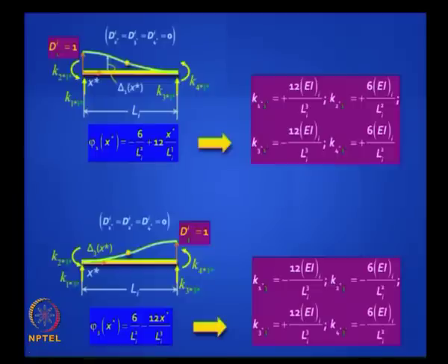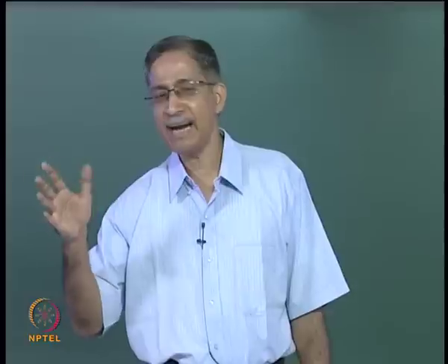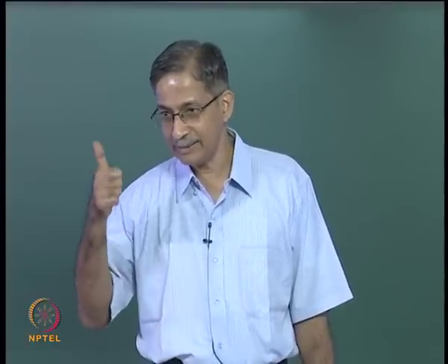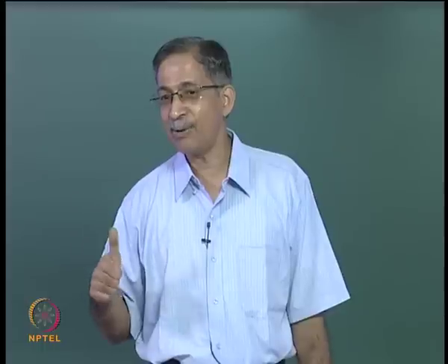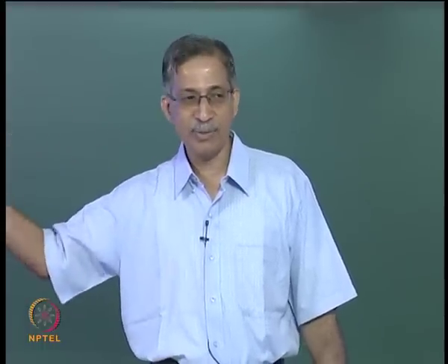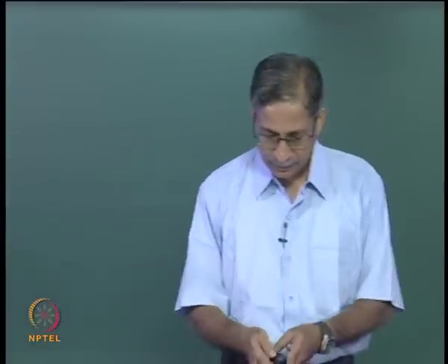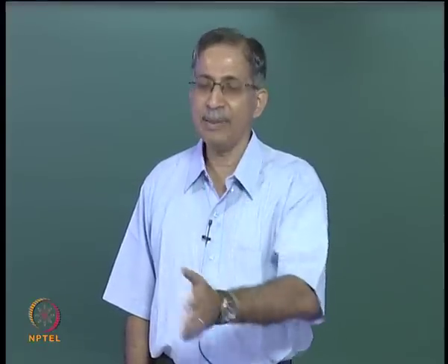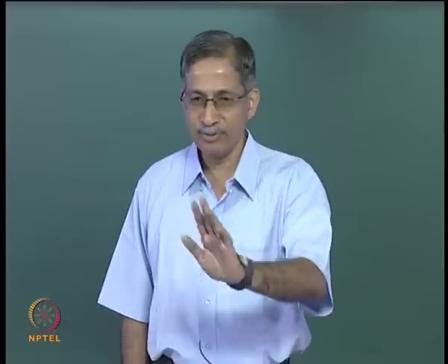Did you get it? I just want you to get the hang of the theory for future applications. Got it? So this is the displacement approach. We calculate the bending moments and shear forces not in the beginning, but at the fag end after we get the curvatures. And so you can do this derivation for all the 4 cases, you get exactly the same results. So we have done 2 alternative ways of deriving this element stiffness matrix. One is the force approach, physically we understand what is going on, we just write down those values.